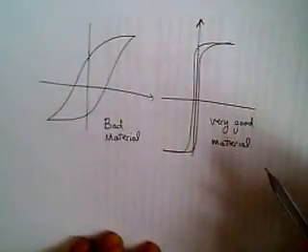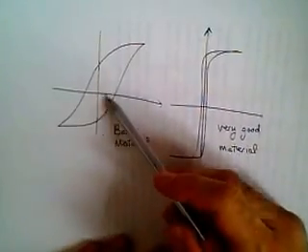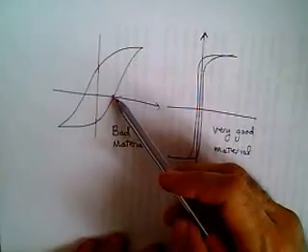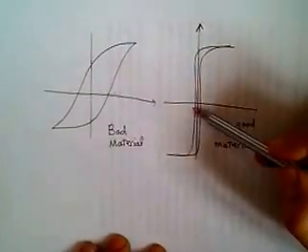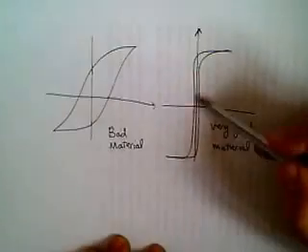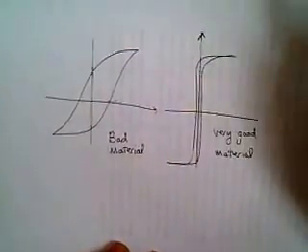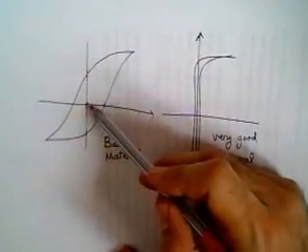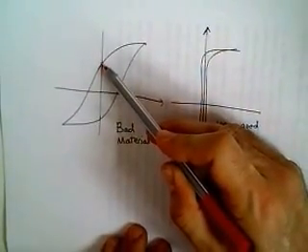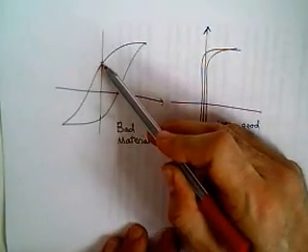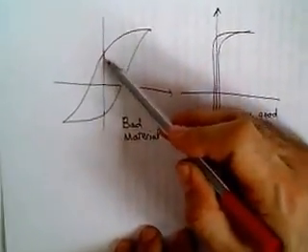So we can classify two types of materials. One ferromagnetic material has a very fat hysteresis curve. The other ferromagnetic material, as shown, has a very thin hysteresis characteristic. For this curve, we have to apply high current to obtain a relatively low residual magnetic field. We can produce permanent magnets, but the efficiency is low.